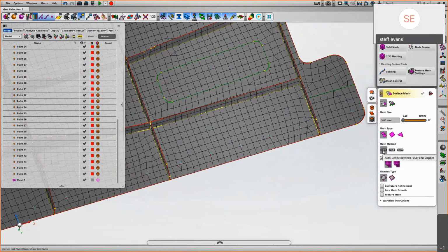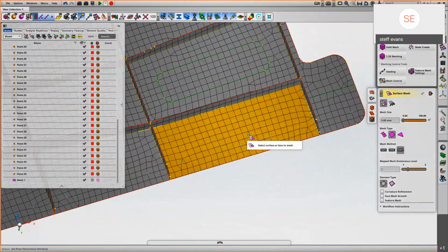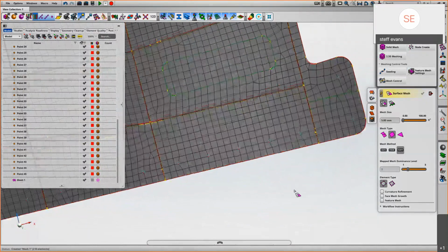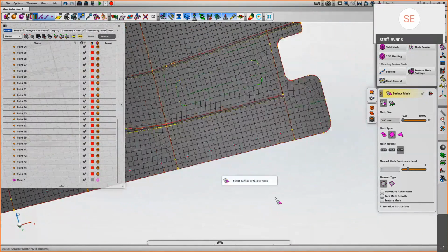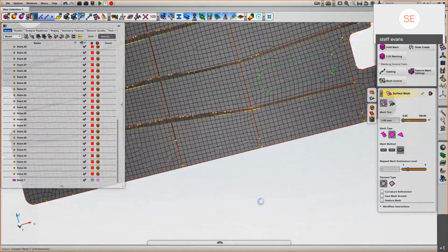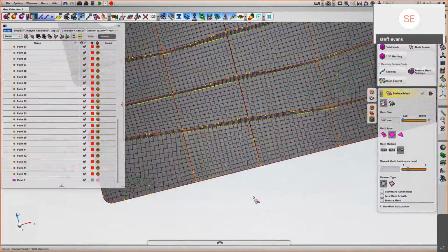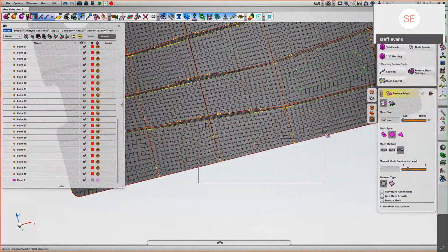So yeah, by default, we've used the mixed mesh with the auto algorithm, but we're now going to switch to the quad only mesh and then the map meshing algorithm. So pick that face, so it's remeshed, and it's given us near perfect quads everywhere, and then just snap the node to the local fastener to give us the definition that we want.